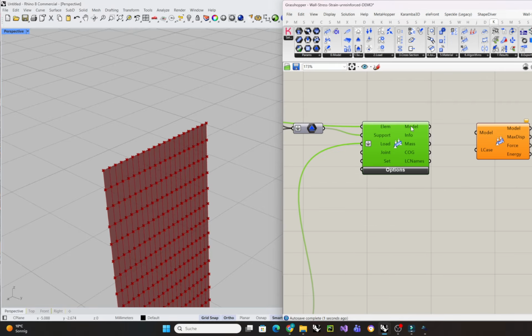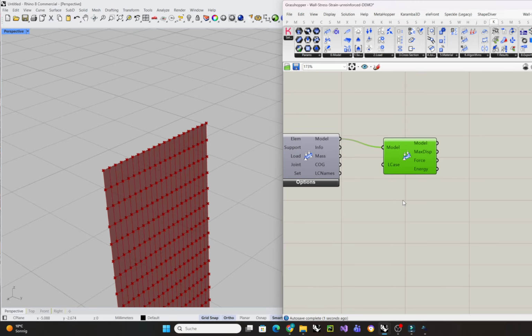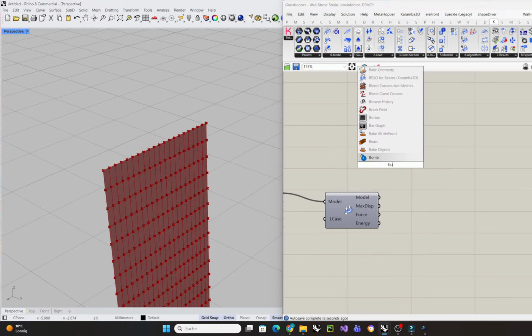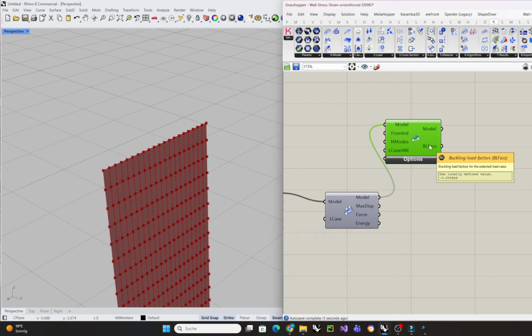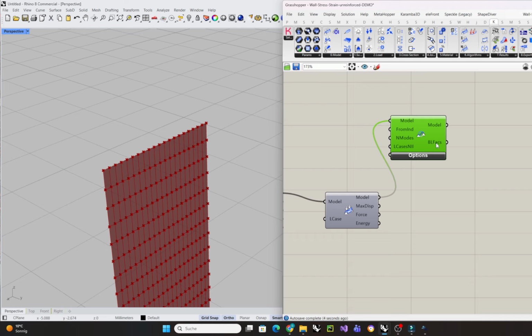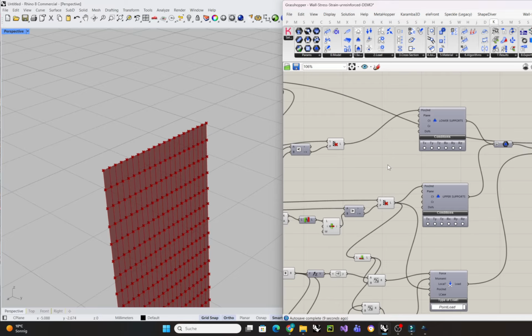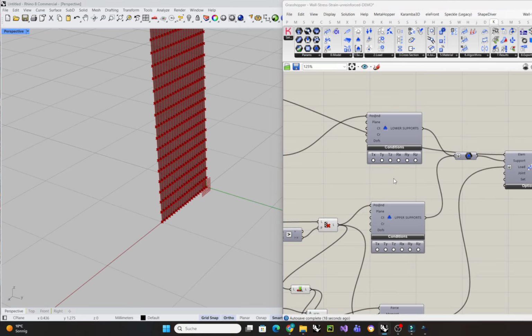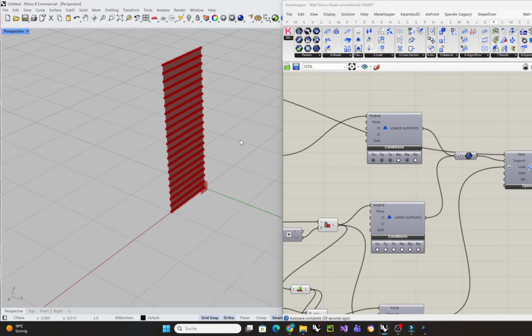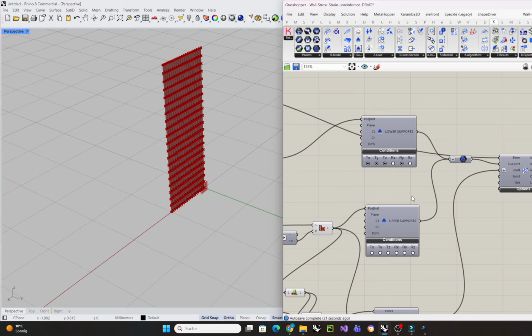Let's just flatten this. Go to analyze model. Let me just check something, buckling modes. Okay, no, I didn't give the support conditions, of course. So let's see. At the bottom, I want to fix all the translations and also one rotation, because the wall will be rigid and can flip otherwise.